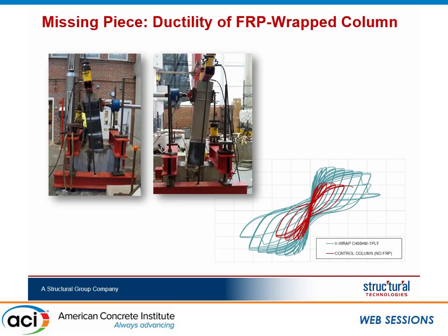When you wrap even one layer of FRP around one concrete column, you get a ductility improvement that is impressive, regardless of how much you are getting on that chart that I showed you. So I told him, if I go through all of the columns of these parking garages and check a capacity design to prevent the shear failure, and I can show you how much ductility improvement I'm going to get by wrapping one or two layers of FRP, will you be willing to accept that design? Because the loss estimator was in charge of approving whatever would be proposed.